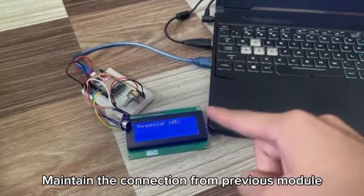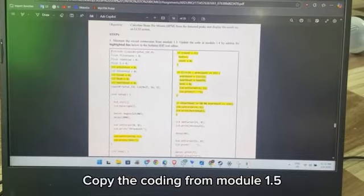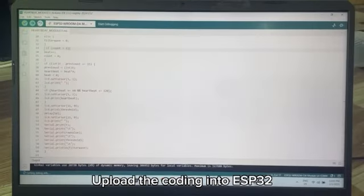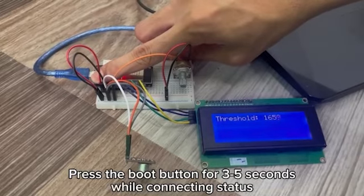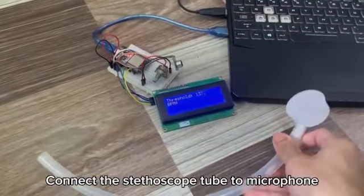First, we will maintain the connection from the previous module. We need to copy the code from module 1.5 into our Arduino and compile the code to check for errors. Upload the code to your ESP32. While the ESP32 is in the connecting status, press and hold the boot button for 3 to 5 seconds. Once the ESP32 is ready, connect the stethoscope tube to the microphone, and that's our input source.